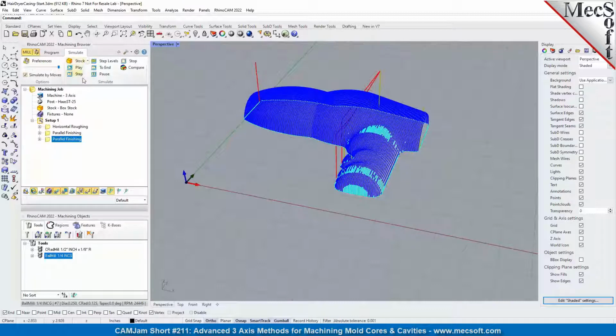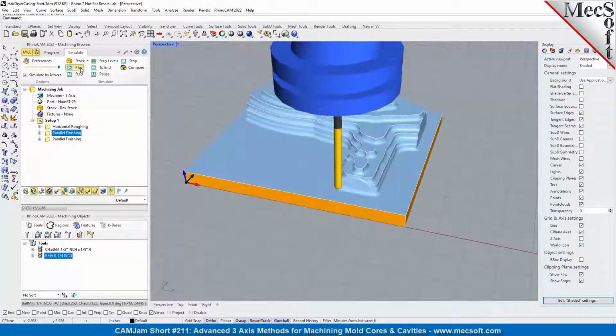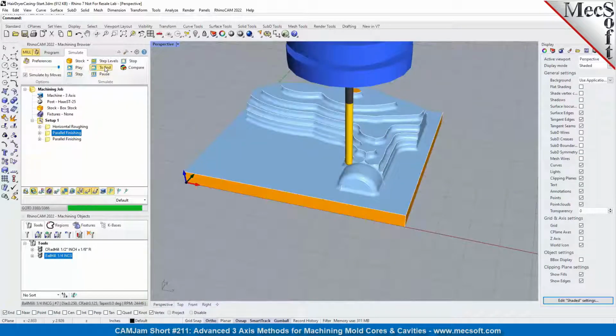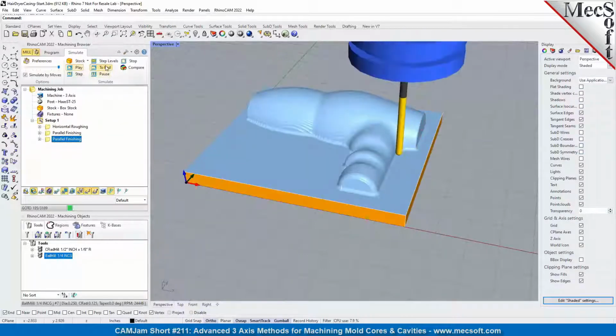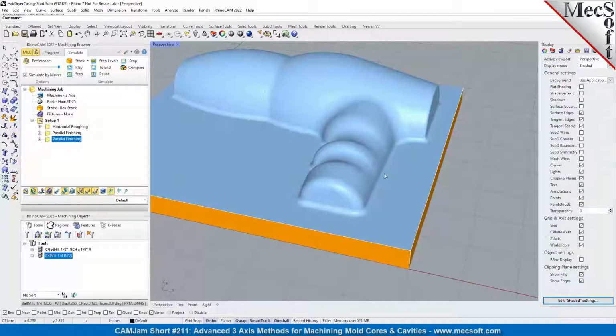Let's go ahead and simulate those two. Let's turn that off, and we'll do pause to the end, and then we'll do this one, and do a pause to the end. So you see, we're getting a good indication of this fillet. It's not exactly done yet, so we're going to add a couple more operations, because you see the fillet on this, you've got vertical walls, which is a true 1/8 inch fillet, but then you've got all these contoured areas that have a bitangent area.